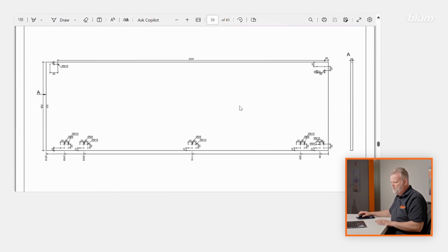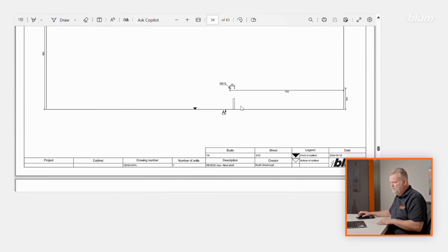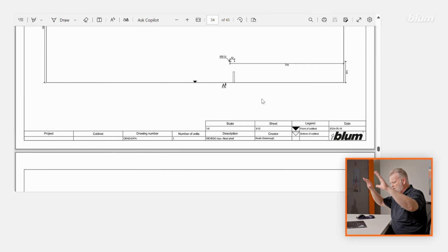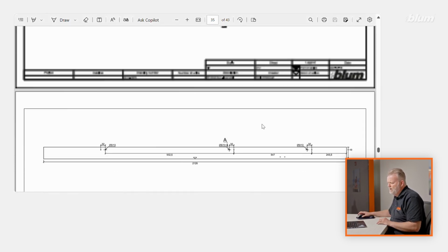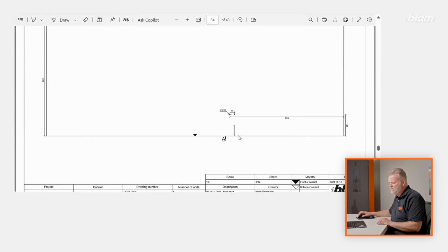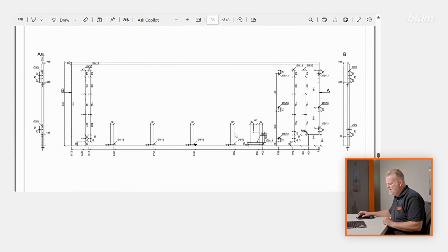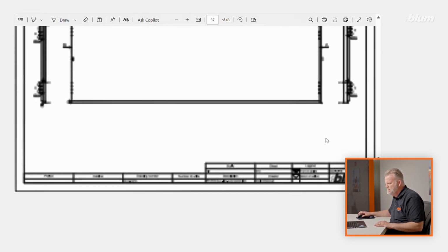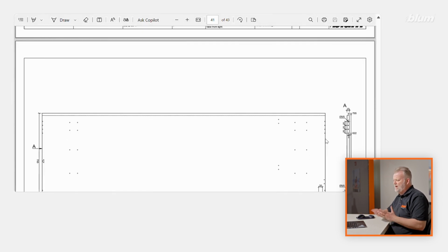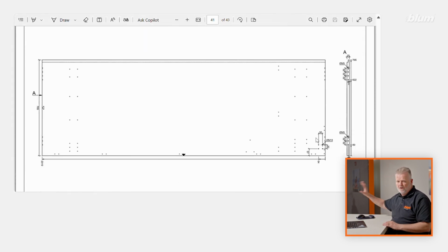Every wooden component is going to be here, including that separation panel or the cross panel, the front decorative panel in front of the rail. Even here, this is that top panel I was just talking about. There's that position for the Uno's TIP-ON BLUMOTION device that gets screwed in. This is showing the cutout for a Duo here, as we can see on the screen. And I mean, this is excellent data. All of it is exactly what we're going to see in the training room when we start assembling the product.